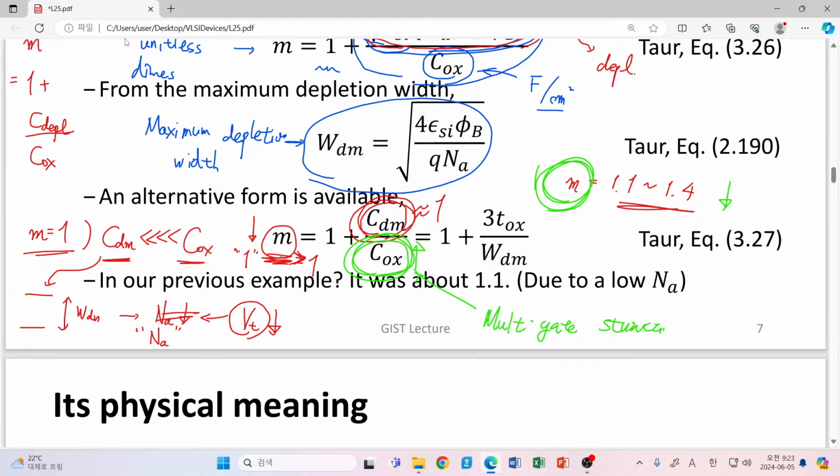Maybe some of you have your own device, and when you characterize your device for logic application, then what is my subthreshold slope? Since the mass production silicon technology can provide us the ideal value 60 millivolt per decade, the competing or alternative devices should be able to provide such a kind of behavior also.